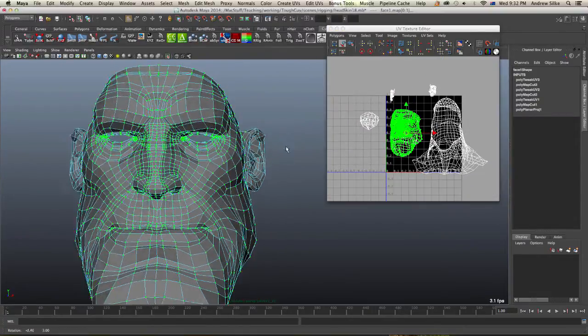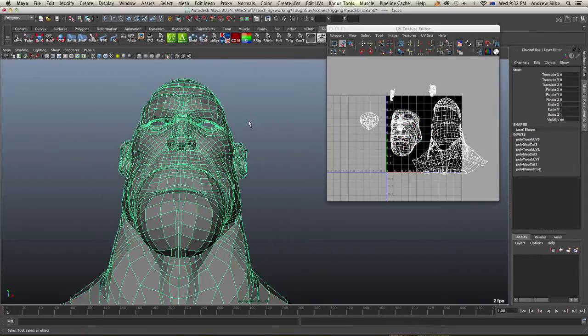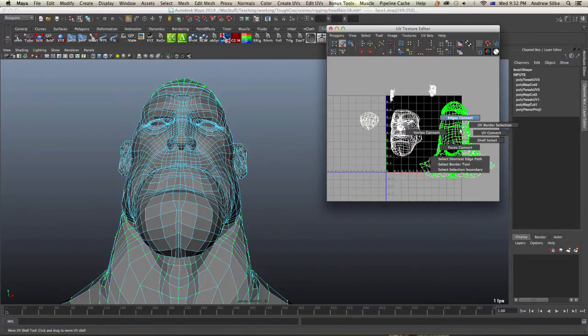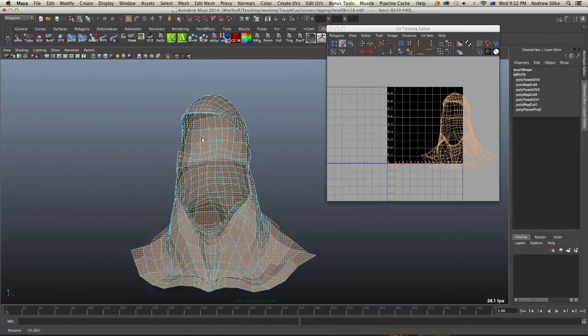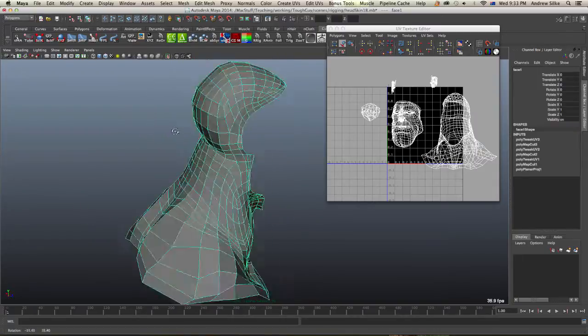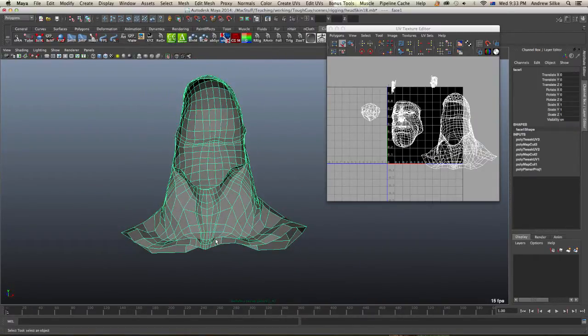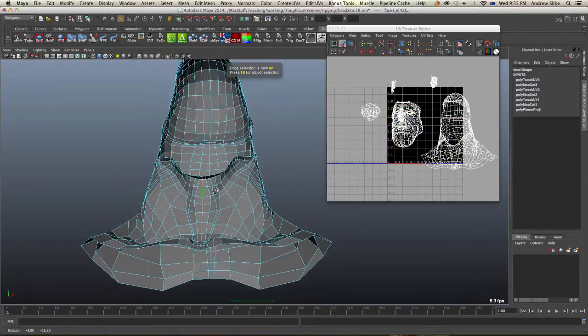And the very last step is just to grab this guy here, the main shell. So let's bring everything back, and this time just select this guy. We can convert into faces. Now we can show him by himself, and we just need to be able to unwrap this a bit like a cylinder. So we need a seam. We can put it down the back of the head. It's a bit shorter in the front, so I'm going to choose that one, just here by double clicking on that line.